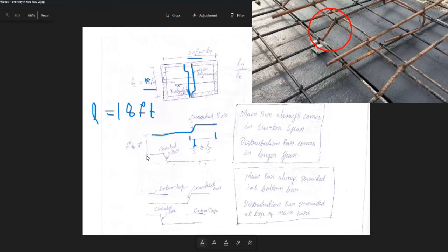And the spacing between bar to bar we need to have is 6 inch to 7 inch. If you are going to design as per IS 456:2000, there we're going to get a bar spacing of around 150 mm to a maximum of 300 mm.